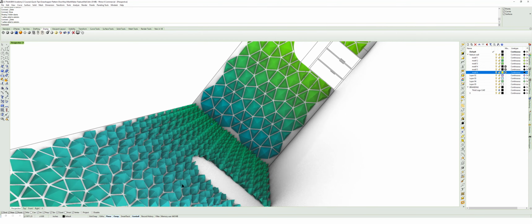And what we want to use it with is the offset command. So I'm going to use this offset curve. You can use the vanilla built-in for Grasshopper, but I'm just going to use the Pufferfish one. It gives me a few more options. Plugging C in, we can see right away a few options. Now, by default, it's actually going out and I want it to go in. So changing the distance, I can right click, go to expression and type -x and commit those changes.